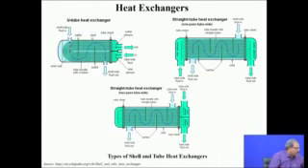So the liquid cannot flow through the baffles, it will come and flow in the small intervening space between the end of the baffle and the shell. The outer one is the shell, and the baffles will force the liquid to take a tortuous path like this, providing good contact, good turbulence and good values of the heat transfer coefficient.